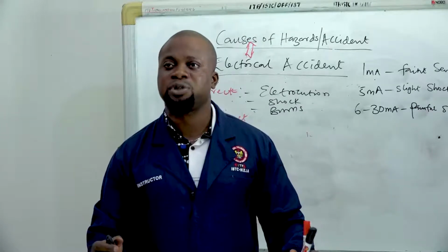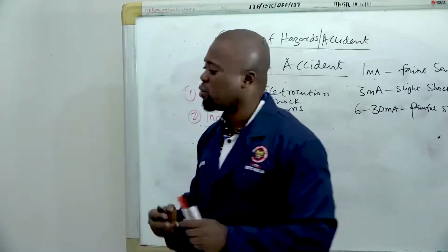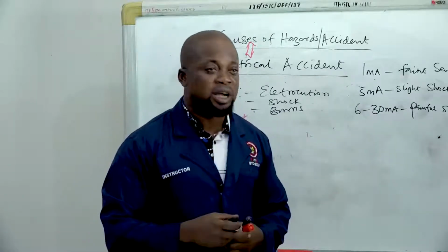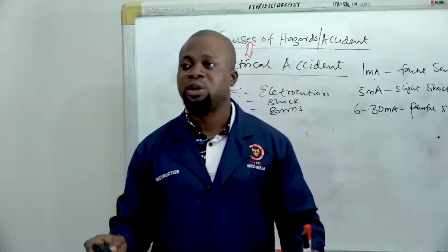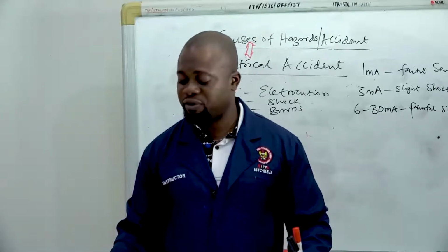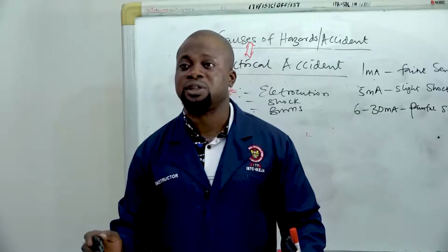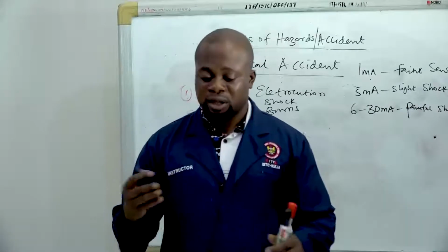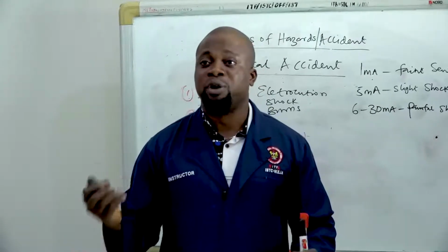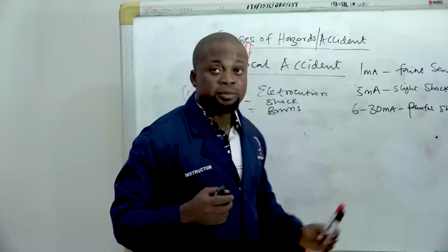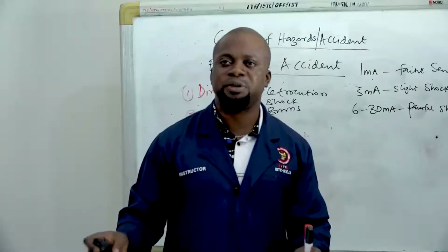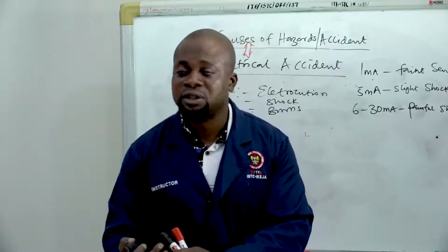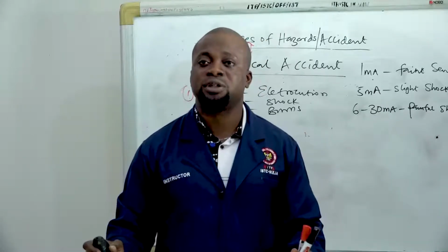So the longer the exposure, the increased danger of shock to the victim. Low voltage, I always say, does not mean low hazard. We need to be very careful when dealing with electricity. Like you can see on the screen, you have a situation of burns. Burns caused by electricity may be of different types. Like I said, we have first degree, second degree, and third degree burns.